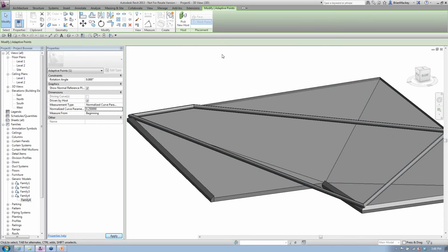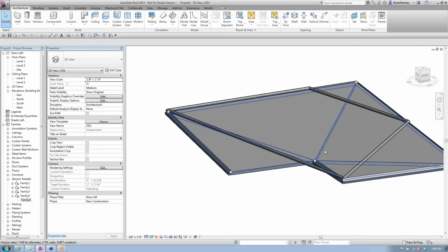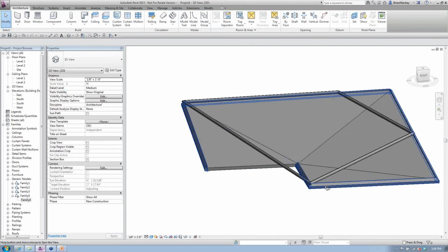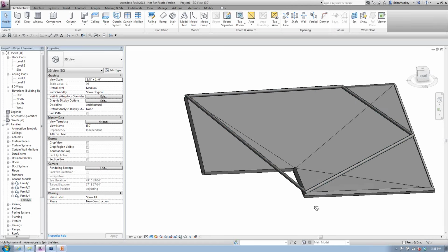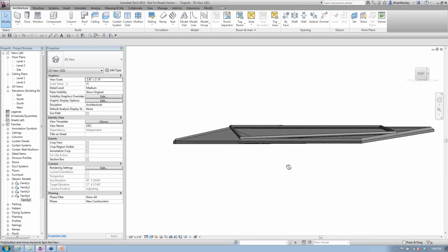You still have the properties of that in the project environment on how you want to be massing it. So I've had clients start coming in and using this for lintels. I've got a window inside of there. I want to go ahead and do a lintel, or maybe I've got this crazy arching weird shaped roof. I'm going to create a component that looks like a structural framing member for the SD phase, and I can just start snapping it to those points, bringing it around. Really some great tools to allow us to start using those adaptive components.